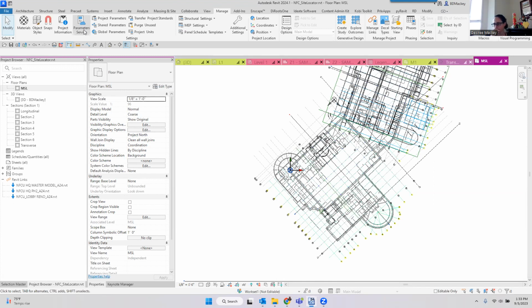I've been kind of liking this, and the reason why is I've had too many companies have multiple versions of their shared parameter file and not know it. Somebody grabbed one that was a year old from some sort of backup folder or something, so they started adding parameters into it. Somebody else is in a different shared parameter file adding parameters to it. And now they've added parameters of the same name. But again, Revit doesn't care.